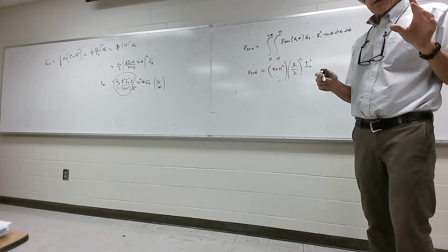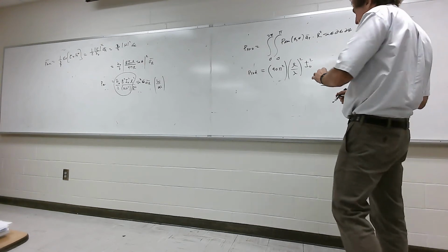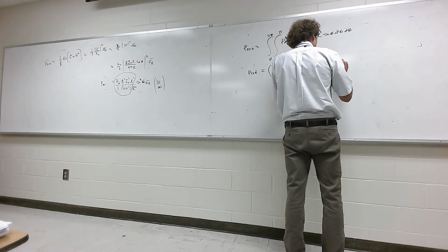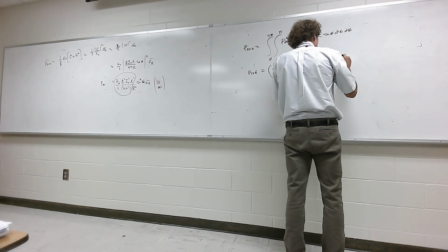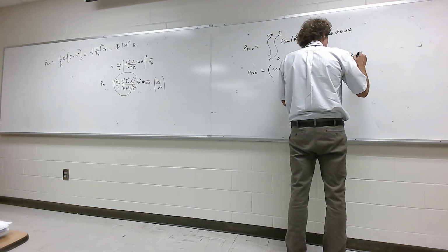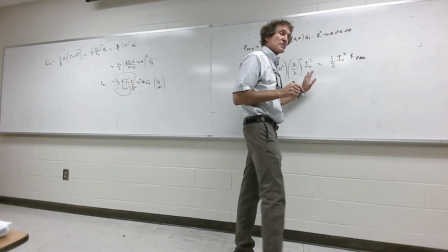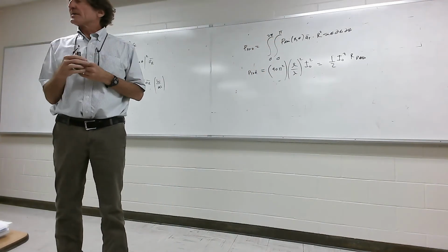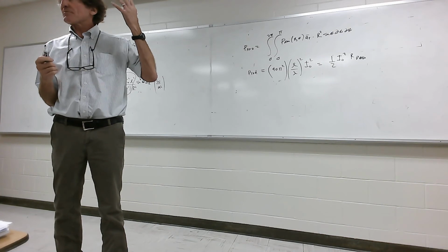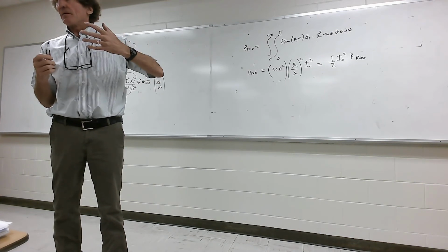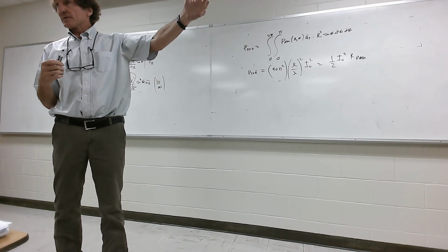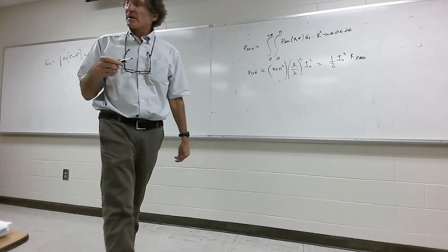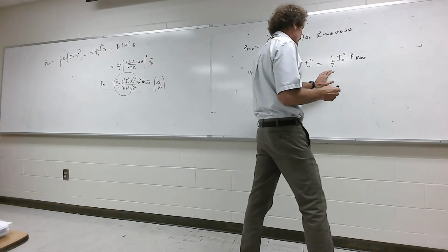So they define that resistance as the radiation resistance. And they take this total power and say that's equal to 1/2 times I naught squared times R radiation. This is called the radiation resistance, and it is, in effect, the coupler. It defines the coupling between the electrical current and the amount of power radiated into the system. It's got to be an I squared relationship, with the 1/2 because we're talking about peak value.